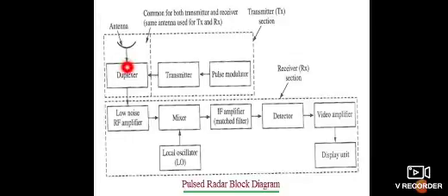The frequency of the transmitted signals is not the same as the echo. The echo signals have a difference of frequency, so the duplexer notes that it is not a transmitting section. That difference of frequency is notified by the duplexer, and it connects towards the receiver, not the transmitter. This is given to the low noise RF amplifier.